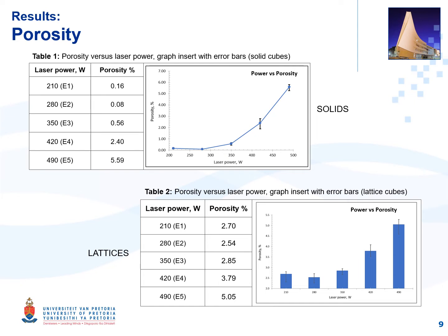As laser power increases further, the total amount of porosity increases, which is due to more keyhole porosity and consistent with previous work done by Prof. Anton du Plessis.